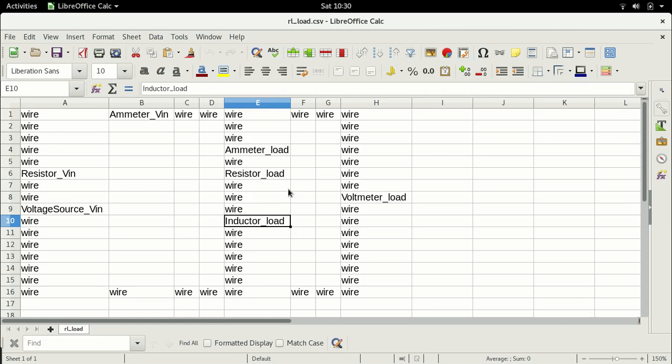This machine can be anything we want. It can be an induction motor, it can be a DC motor. Well, it can't be a DC motor if it's an AC source. It has to be an induction motor or a synchronous motor, or if this is a DC source, it can be a DC motor. Or if this is a three-phase AC source, it can be a three-phase induction motor or a three-phase synchronous motor. And if you are interested, you can also simulate some of the more advanced machines like switch reluctance motors and several others. Again, all this will happen bit by bit.